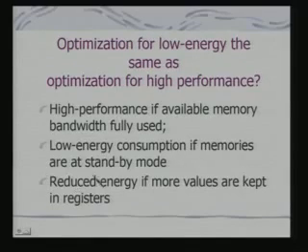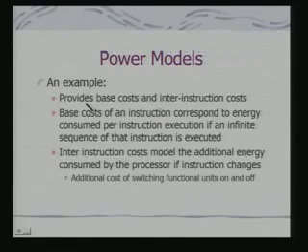Now whether you can come up with these kinds of strategies would depend on whether you have an appropriate power model to characterize the execution sequence for a processor. So a power model actually provides you with a pattern in which energy will be consumed during execution of instructions. Let's take an example of a power model. It would provide what are called base costs and inter-instruction costs.